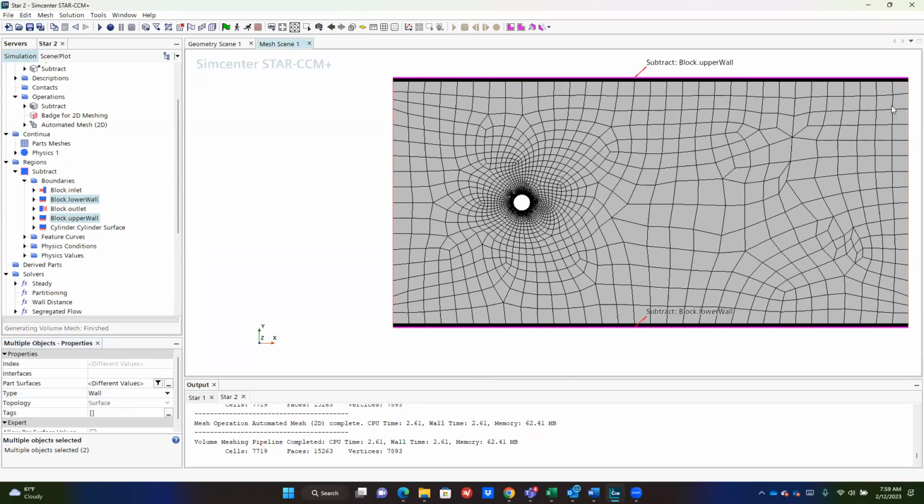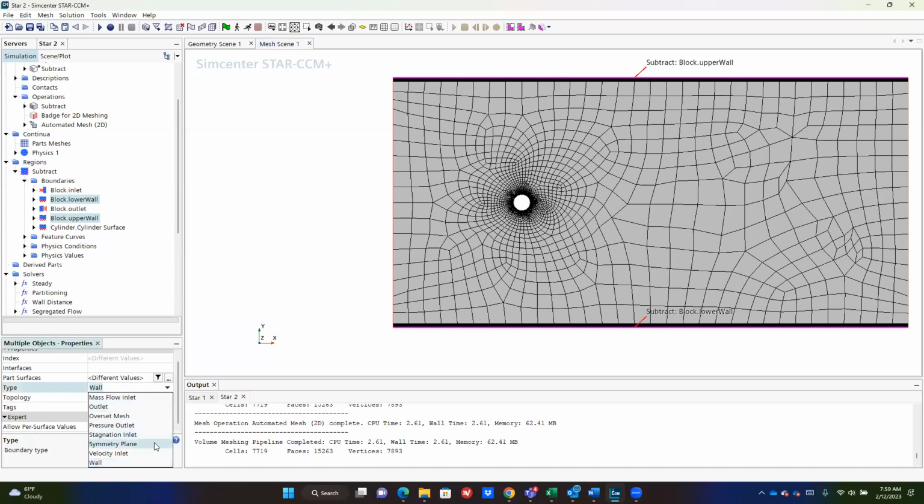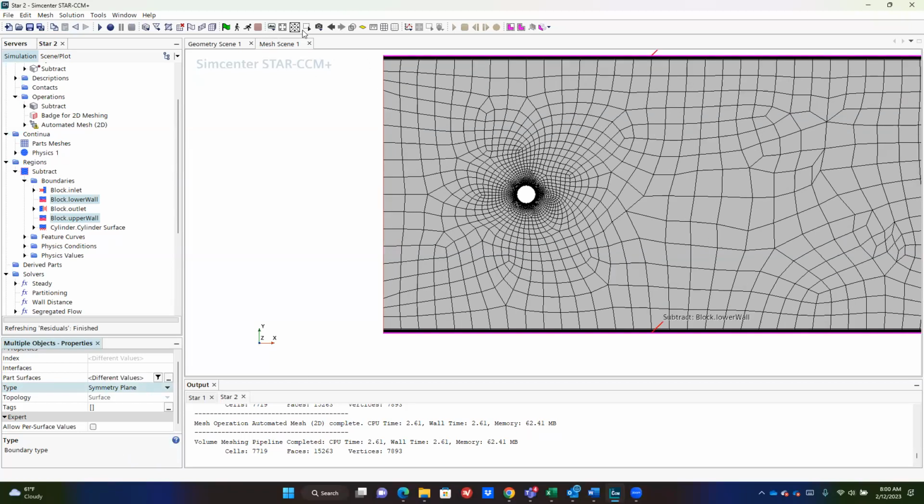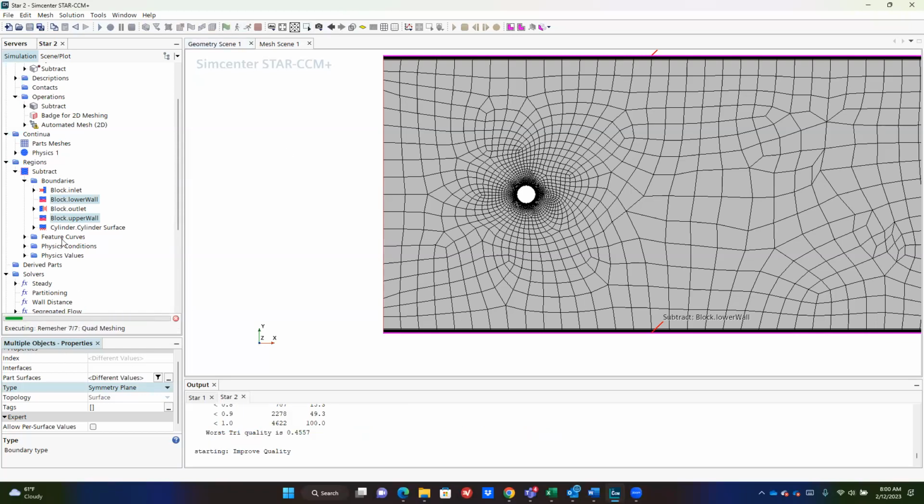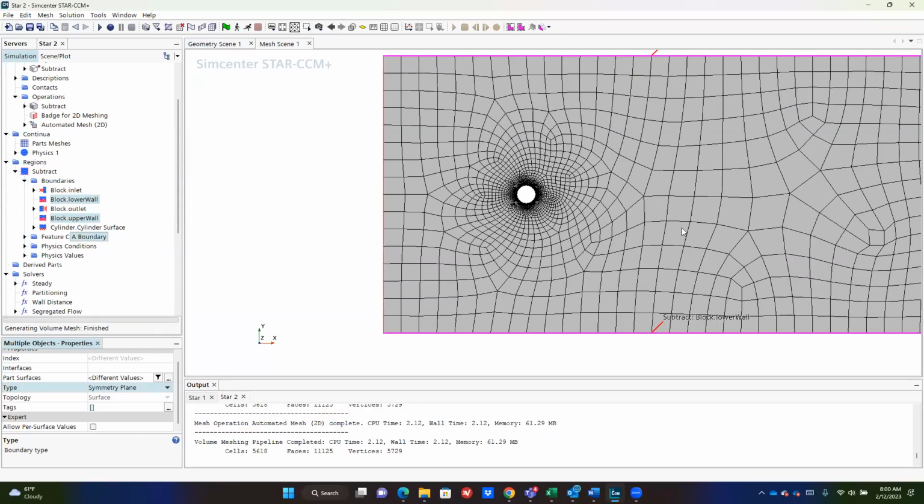But it takes a lot of effort to model these small boundary layers, and the boundary layers aren't that important for the most part. Because of that, I typically just use a symmetry plane, and it looks like an inviscid wall, and you get away with the blockage effects in the wind tunnel, but you don't have to worry about boundary layers in the wind tunnel.